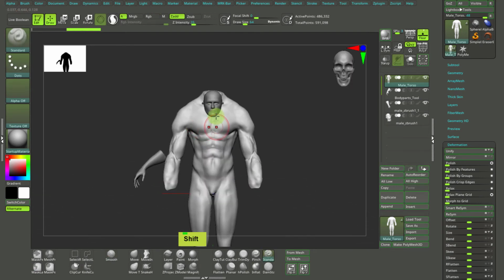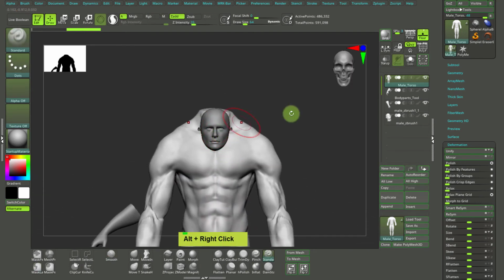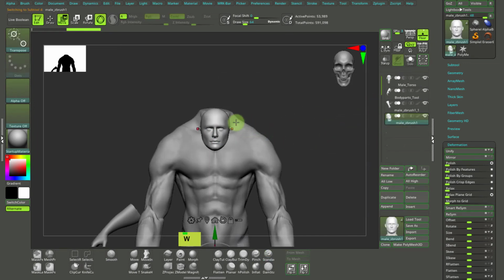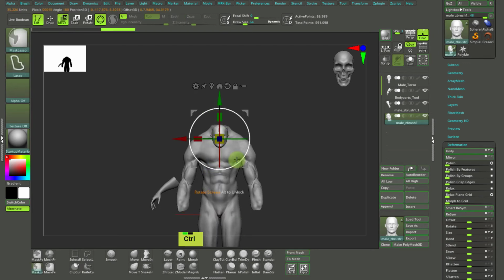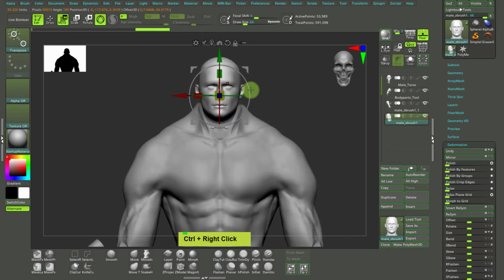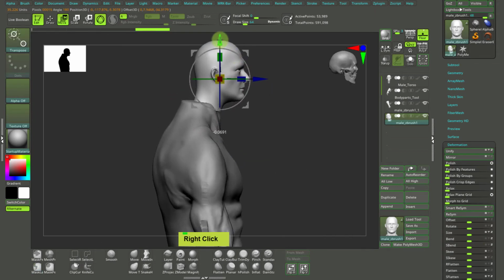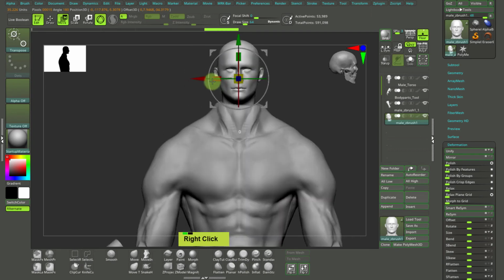Okay, so first of all, just let me select the male head, press W and holding down Alt, and I will turn off symmetry, because it is a little bit easier to snap to dead center if we have symmetry off. I'm holding Alt, clicking on the relocation, and pulling this up, and pulling, and just going in.